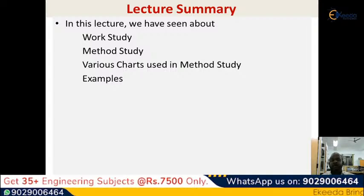At the outset in this lecture, what we have seen was what is meant by work study. Work study is a combination of method study and work measurement. How I am going to do that work, and how I am going to measure the work that I have done. Then what is meant by a method study, where it is being used. What is the entire procedure of making a method study? You have to analyze the particular work and make an objective. Then you have to record what is happening over there. Then try for a new alternative. Then establish the new alternative and check its performance. All this is done in the method study.